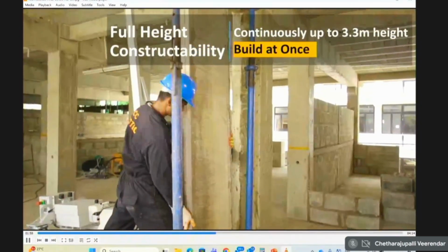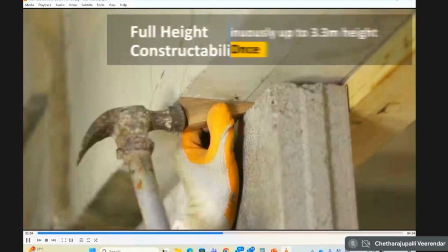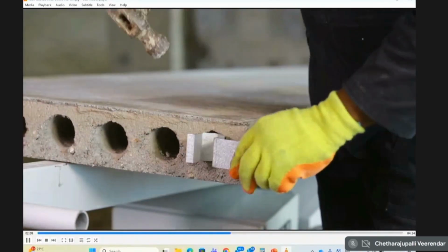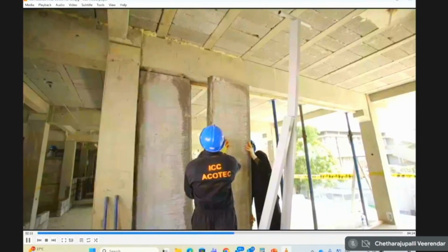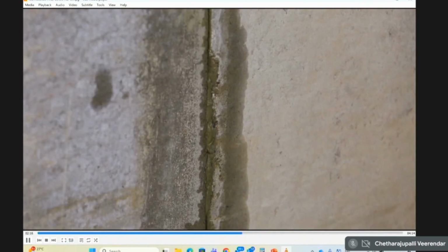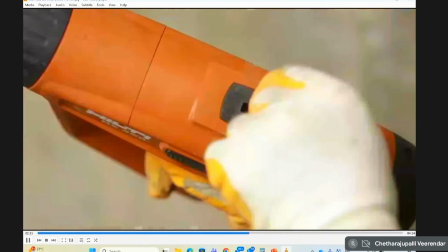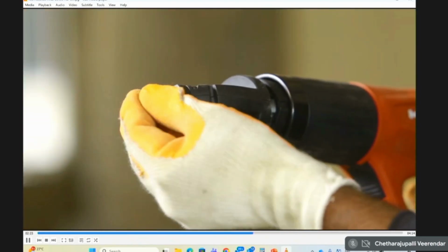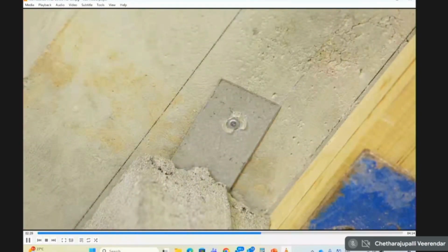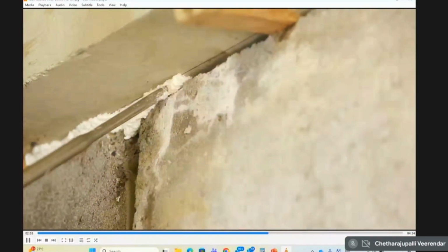And then you toggle it and fix it. At the bottom there is a mortar. On the top there is a gap which is filled with PU foam. On the left and right side you have this tongue and groove. That small V section is drilled in for stability in the beam, but it is not connecting to the top because it's a non-load bearing wall.